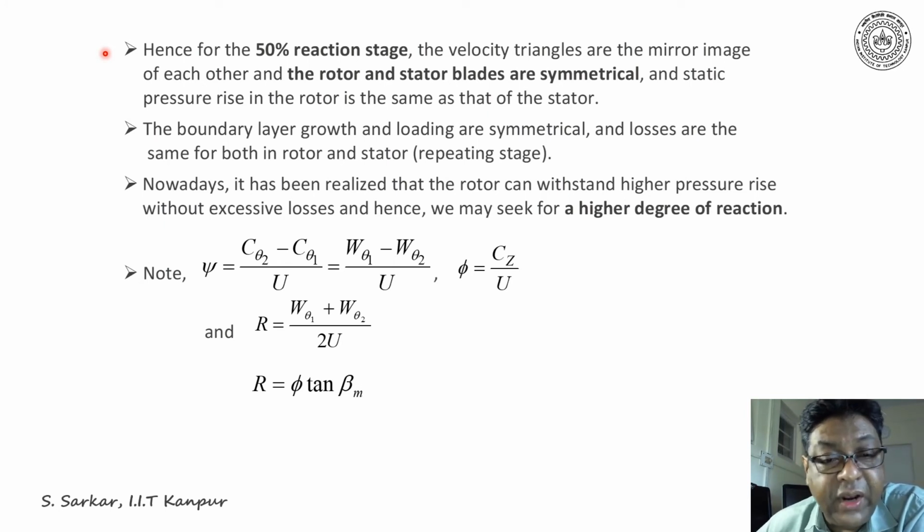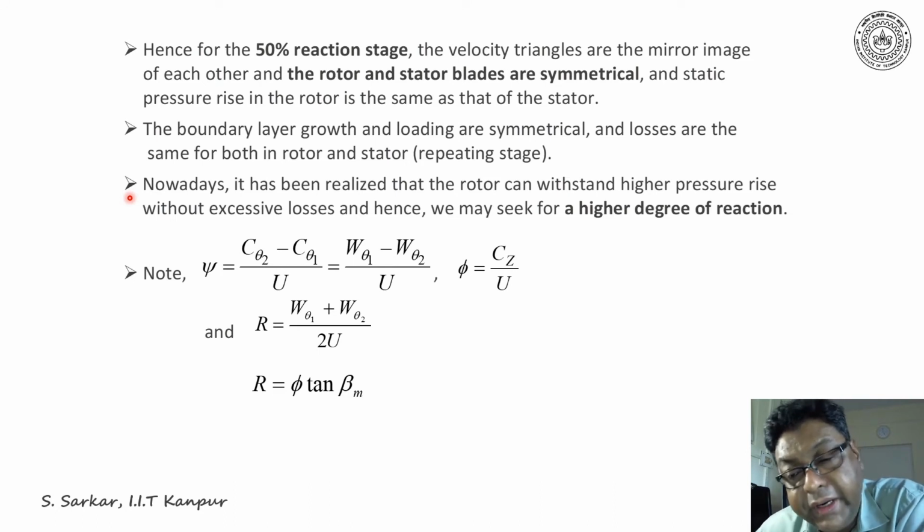The static pressure rise in the rotor is the same as that of the stator. Furthermore, the boundary layer growth and loading are the same, and the losses are also the same for both rotor and stator. So thus we are leading to the repeating stage. Nowadays, it has been realized that the rotor can withstand higher pressure rise without excessive losses. Hence, we may seek a higher degree of reaction.